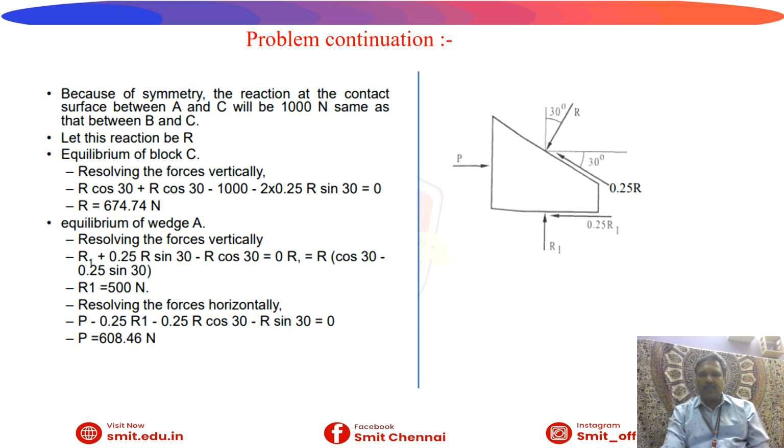Then equilibrium of the wedge A we are also going to take. Resolve the forces perpendicular to the plane. What are the forces? R1 plus 0.25 R sin 30 degree minus R cos 30 degree equal to 0. Upon simplification, you will get R1 equal to 500 Newton.